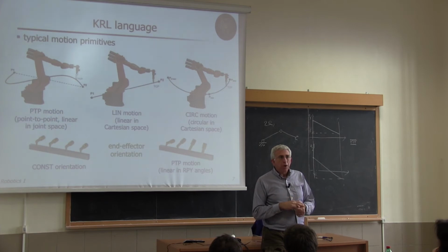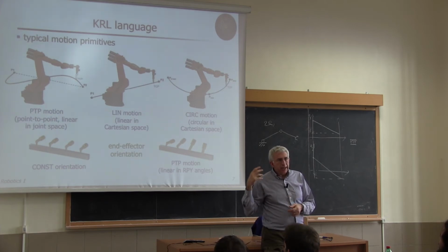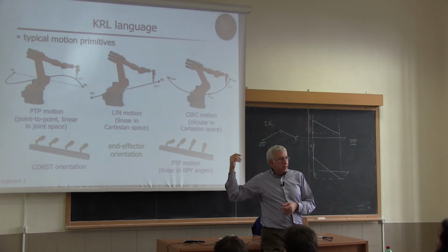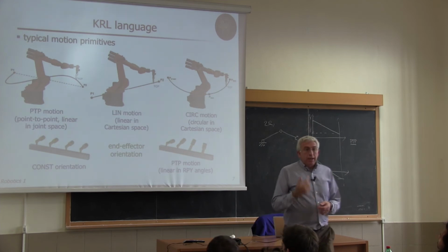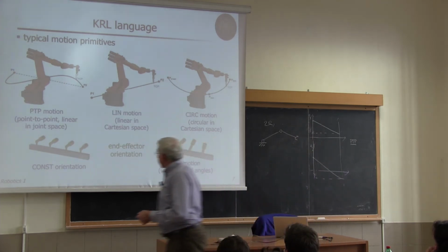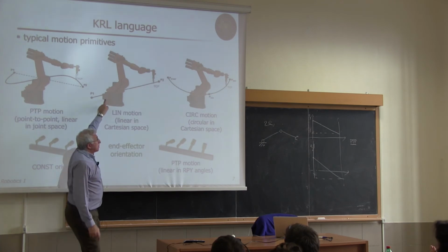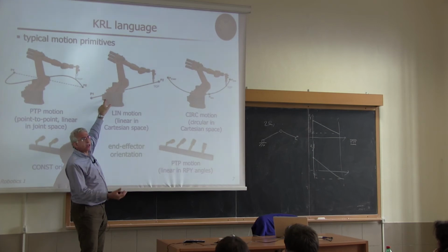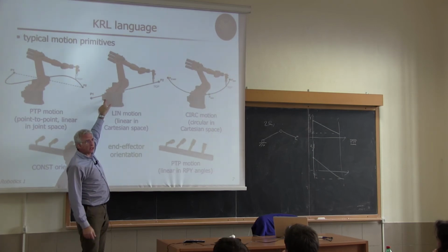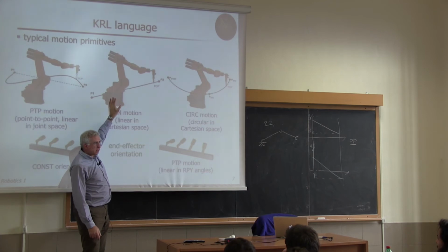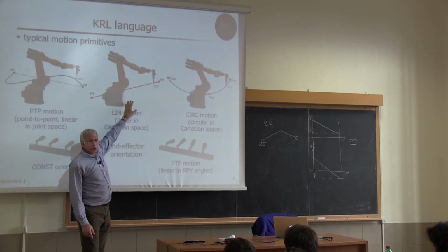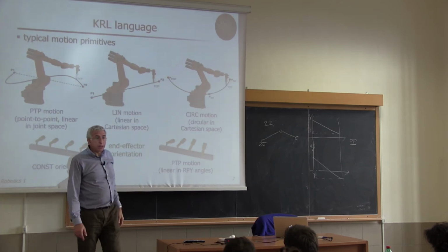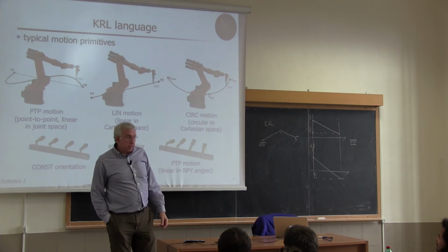So remember that all the analysis is not thrown out of the window, even if we can program that way. In fact, the KUKA controller receiving such types of commands will do exactly what we learn in this course about inversion and inversion at the differential level, checking things and trying to stop the motion in advance or modify the motion so that the robot can go through singularity in a robust way.